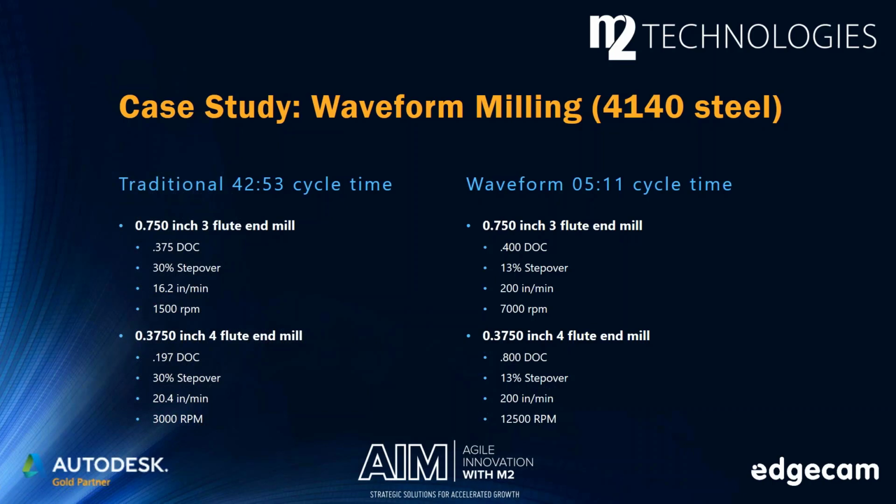When we used the same exact tool, same geometry with waveform, we achieved a much shorter cycle time on exactly the same part. There was no wear on the tools, chip formation was great, the cutting performance was much better, and look at the cutting rates we were able to achieve. Slightly deeper depth of cut, lighter step over, much higher feeds and speeds with the larger tool, and also with the smaller 3/8 cutter as well.